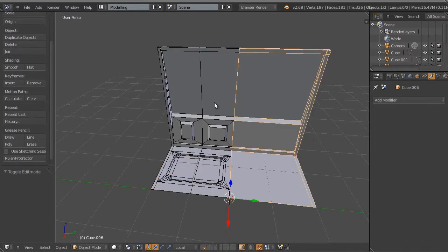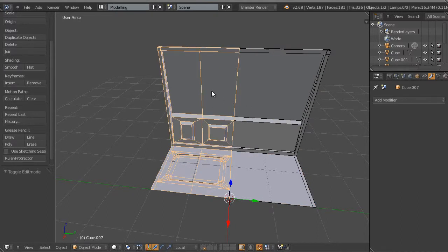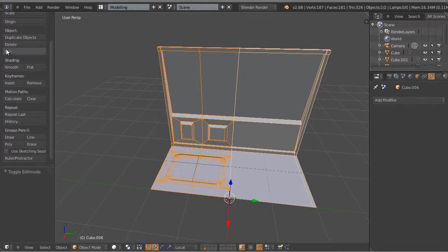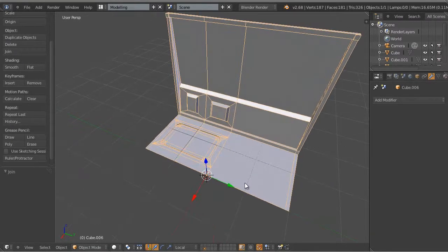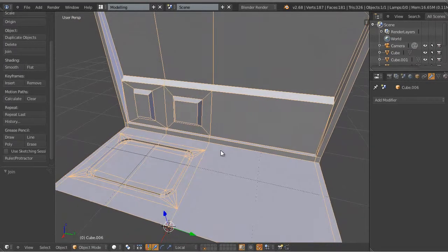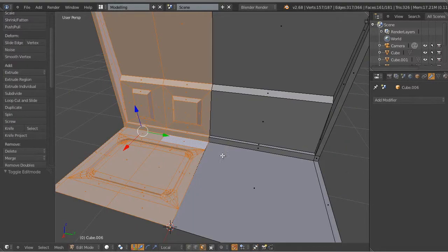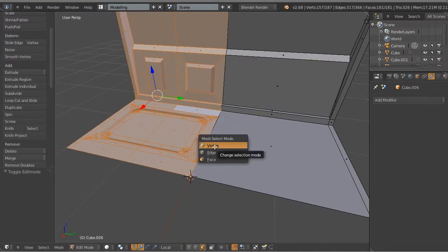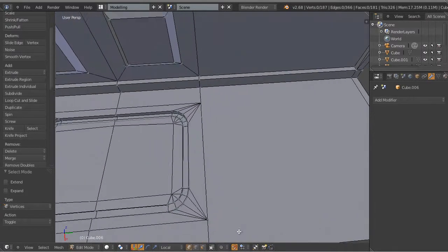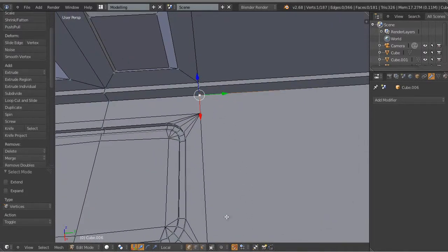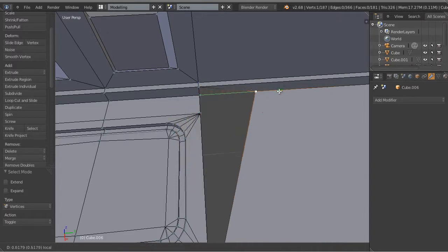But of course these are still 2 separate mesh pieces. I can join them together into one mesh by selecting both meshes and choosing Join. And now these 2 meshes are combined together in one mesh. But of course if I open up sub-object mode again, the edit mode, by choosing Tab on the keyboard, and I move to vertex mode, you will see here that at the vertex level, let's just turn off snapping. If I pull these vertices apart, they're not connected or joined together.